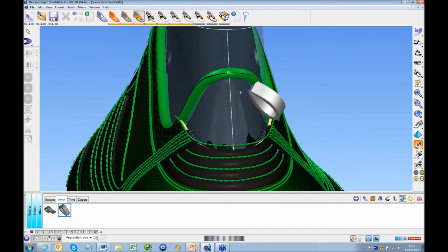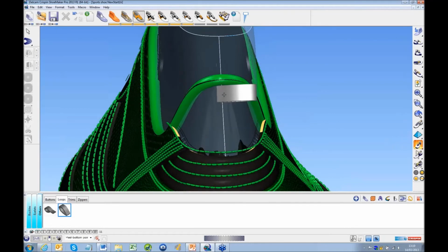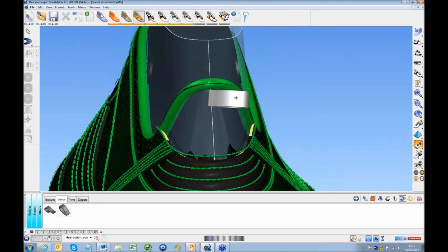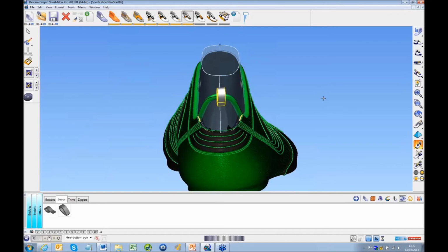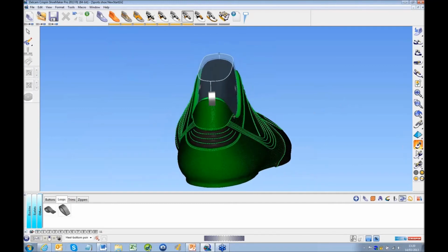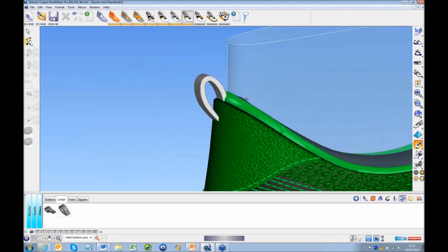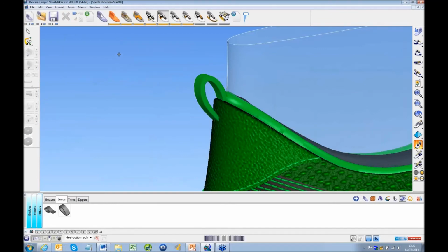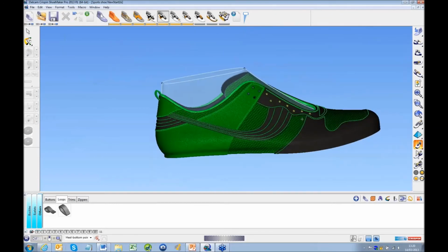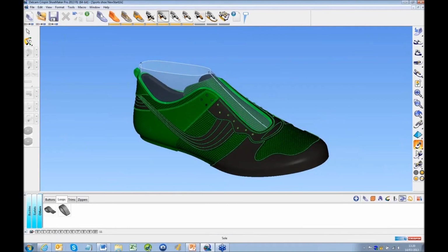I'm going to select the accessory I want to apply to the design, so in this case this loop. I can interactively position the loop. I'm going to select the loop and change the orientation. So here I'm dynamically rotating the loop until I have the orientation as I want it. I could also dynamically change the size of the loop if I wanted to as well. So it's now in place. The final thing I have to do is to color code it. So again, I can use the copy properties to copy from the pipe onto the loop to color code everything accordingly.